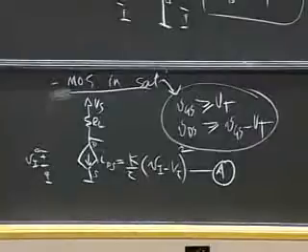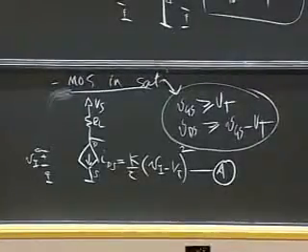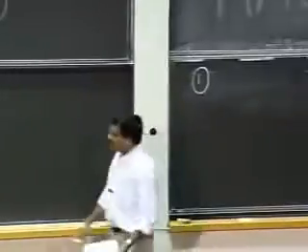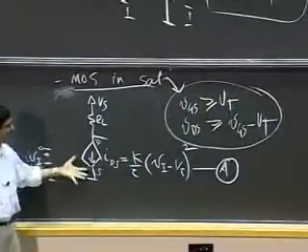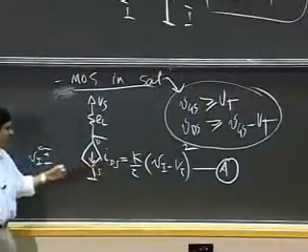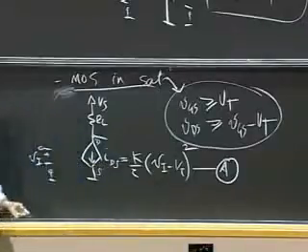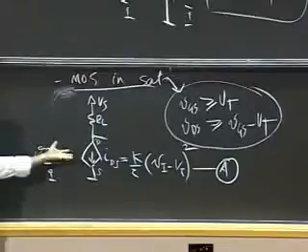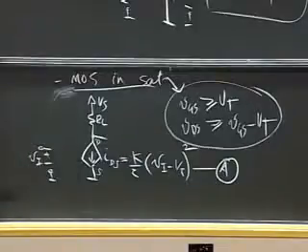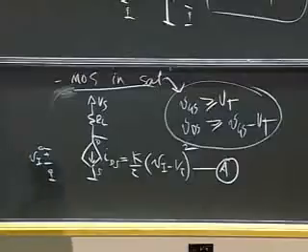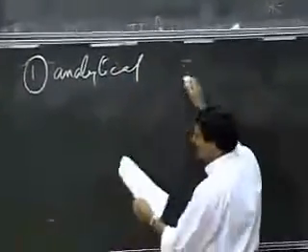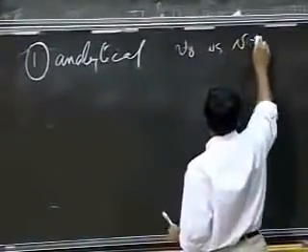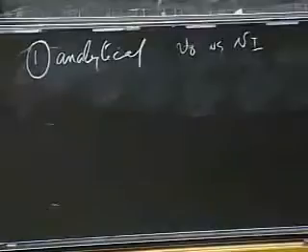So with this new little circuit with the MOSFET working as a current source, let's go ahead and analyze our amplifier. Notice that to analyze this circuit, I have a current source. It's a dependent current source where the current depends on the square of the input. So this is a nonlinear circuit, and I can apply any one of the methods that we talked about last week for nonlinear circuits. To analyze it, I'll go ahead and use the analytical method.